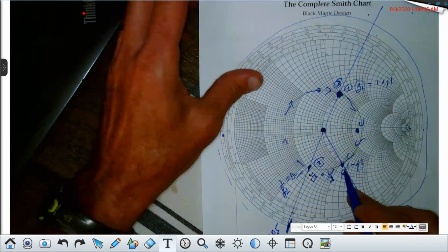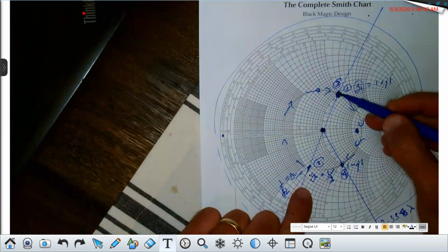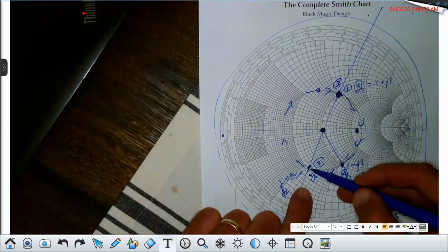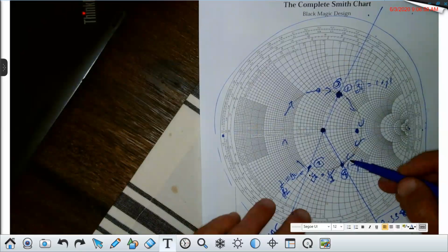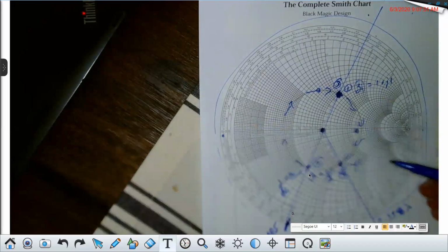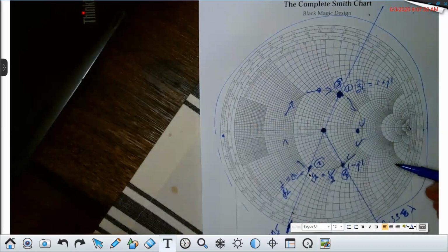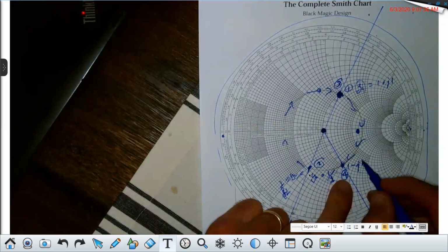Right? We moved from here. First, this is our input impedance we came in at, 1 plus J1. We took 1 over that, we get 0.5 minus J0.5, right? Now we move until we get an, not impedance, admittance of 1 minus J1, right? How many see that? All right. We've got to get rid of this, right?